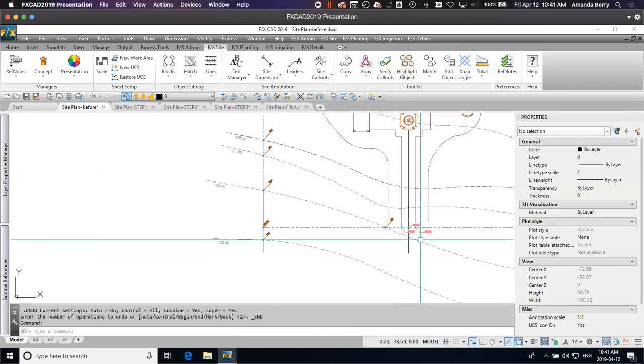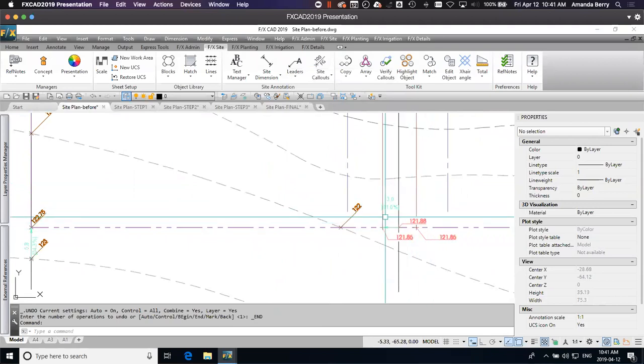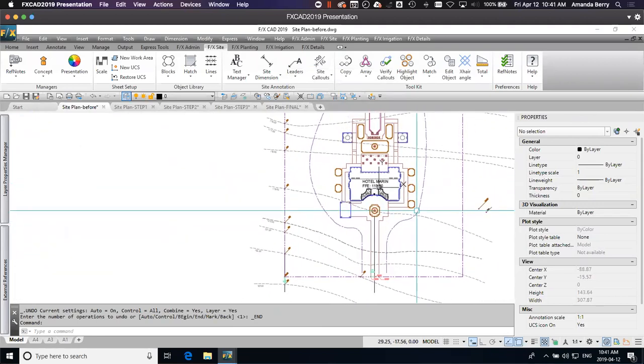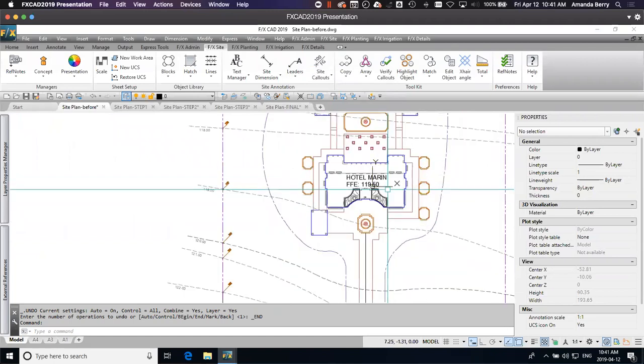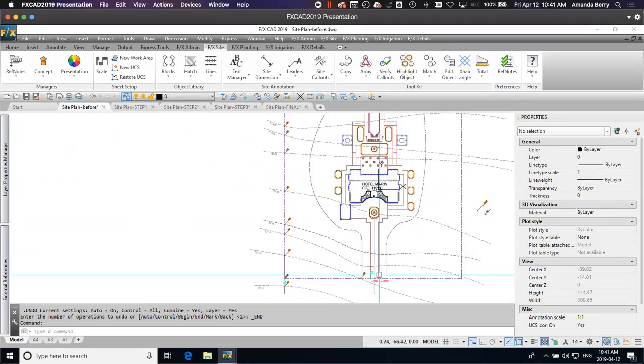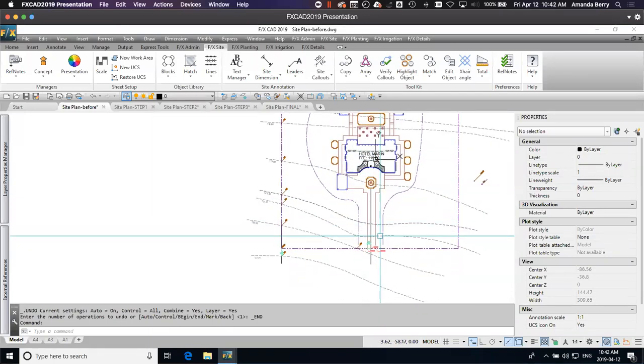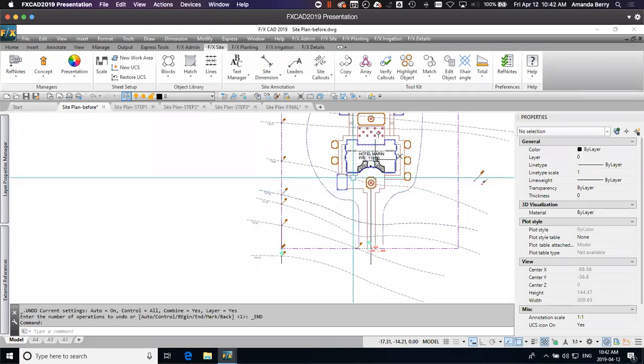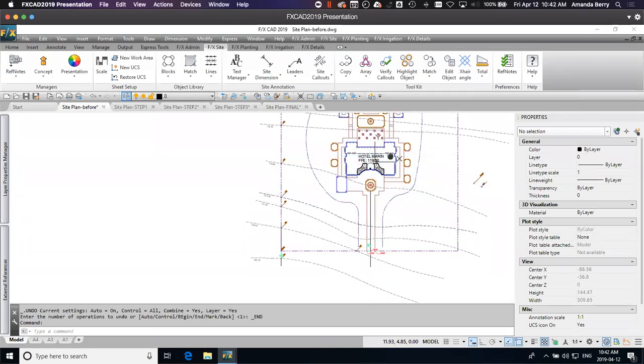So we've determined a few points along here, as this is one of our pinch points that we identified before, but a lot of our other pinch points are closer to the building. So I'm actually going to change gears over to the building. If you didn't have a finished floor elevation, you might at this point start making some moves going down this driveway to determine what your finished floor elevation might be.